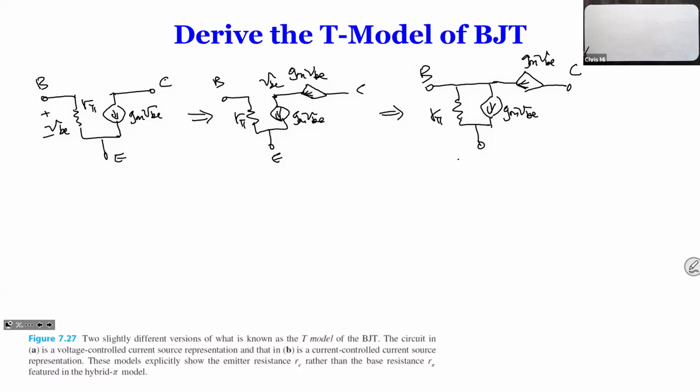So we do that, it should be fine. Yes, go ahead. If they don't have the same amount of current, say one has 1 amp and the other has 2 and you put them in series, it's like plugging in two voltage sources of different voltages in parallel with each other. One will try to charge the other, and that current has nowhere to flow, so the voltage is going to start to increase, and then eventually it's going to break.